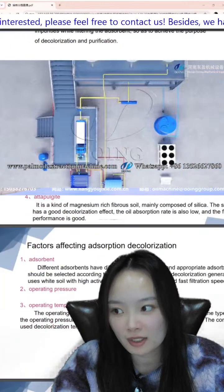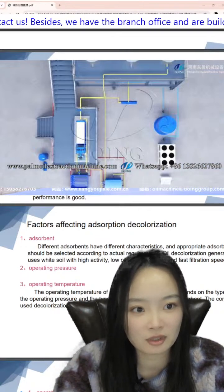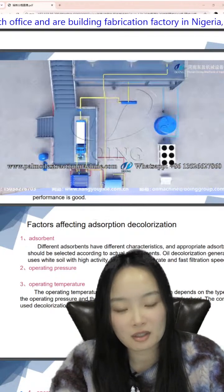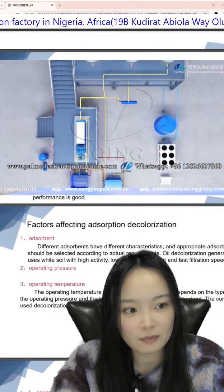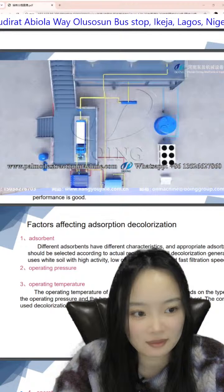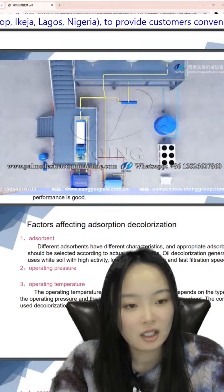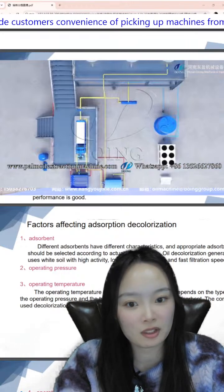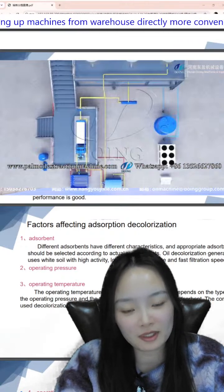Let's move to the next one. There are some factors affecting the absorption decolorization, such as the absorbents. Different absorbents have different characteristics, and the appropriate absorbents should be selected according to actual requirements. Oil decolorization generally uses white soil with high activity, low oil absorption rate, and fast filtration speed. And second is operating pressure. The third one is the operating temperature.